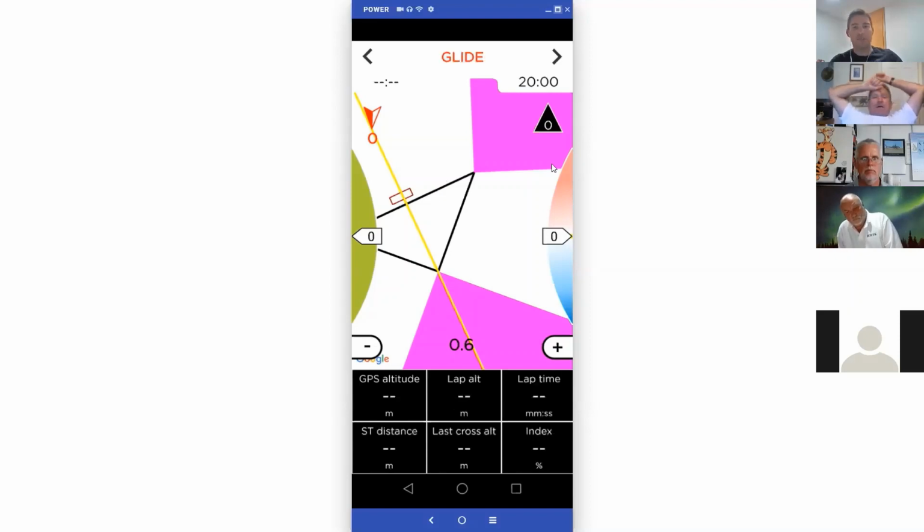Basically, when I fly glide page, again, I have here GPS altitude. I have on all pages over here GPS altitude. Why? I fly a Raven and Snipe for the scale, and I fly Sparrow and Snipe on the light class. So when flying scale class, I have always my airspeed indication, which tells me basically my true airspeed, and this is what I want to have for my best LD. I should fly around 70 kilometers per hour.